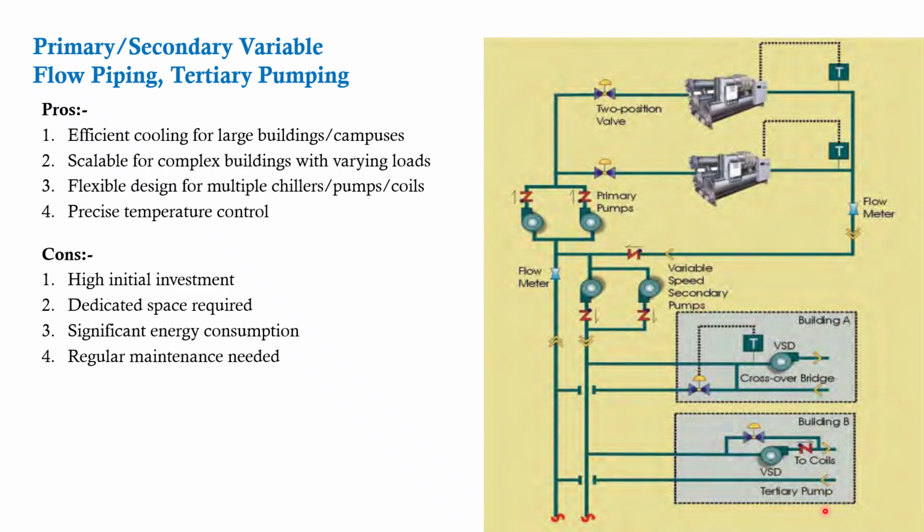It requires more maintenance because the number of equipment has increased. And what should be the control strategy, how the tertiary pump and the secondary pump need to be regulated in this kind of configuration. Constant flow is simple and less efficient, but it is going to consume more.